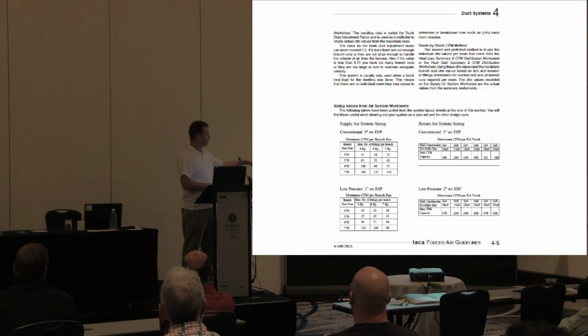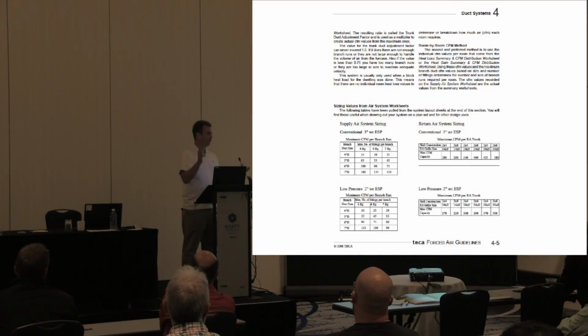But if we get to a heat pump, depending on the manufacturer, the range is a little less, so we oversize the ductwork a little bit to keep the noise down and to make sure the flow across the coil is good enough that it doesn't overheat the compressor and then cause longevity problems or efficiency problems, because we don't want it to overheat. A heat pump will run at 100, 105 degrees Fahrenheit, whereas a furnace can run at 140, no problem. And oil, for those guys that are still putting in oil, can run even hotter, 160, 170. So you have a little more range with the furnace, so we just got to make sure of that.